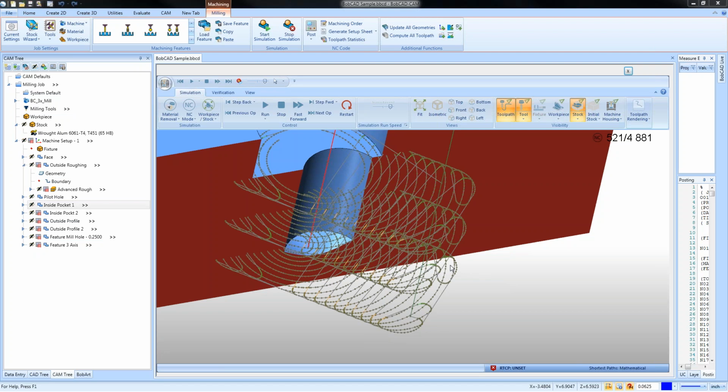Can we rotate an STL file to be used as operation stock in the editor for Op2? If you're using STL stock, you don't select STL stock from the screen. You select STL stock from a directory. If you wanted to modify the STL stock, you could open up the STL, rotate it, save it, and then when you're assigning it as your stock, it would be in position. So that's how you would handle that.